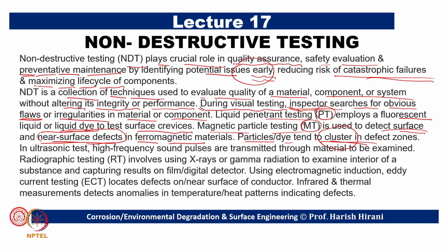Coming to the other testing, where we can look at subsurface cracks, or through and through complete surfaces, we have the ultrasonic test, the radiographic test, the electromagnetic induction technique, and infrared thermal measurements. In this present lecture, we will be covering more about UT, that is the ultrasonic test, which is basically a high frequency test. We will be detailing that.